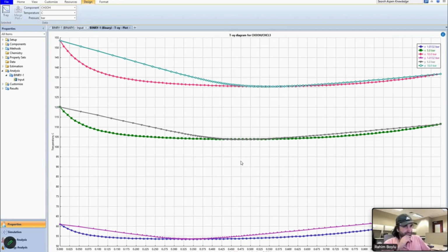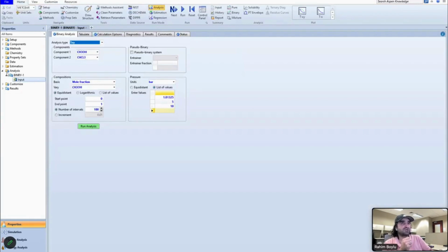And if vapor and liquid curves are getting closer, it means you need to add more stages for distillation. Also, if they meet at a place, it is called an azeotrope, but it is commonly also called a pinch point. So you can use these terms. I think that's all for this graph. So we can go to the simulation section.